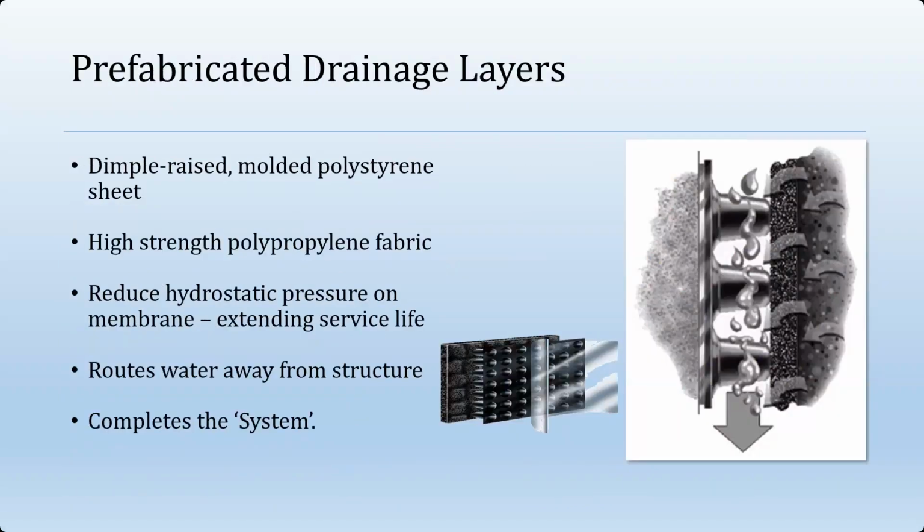And prefabricated drainage layers. These are systems that are used for multiple purposes. They're used to protect the waterproofing, but also, more importantly, they reduce the hydrostatic pressure on the system, and they might also extend a warranty. These are always a good thing, and I always bring up the question that I suspect will be for the ages. We get this question almost every other month: where do we as the manufacturer advise placing the drainage mat relative to the foundation insulation?